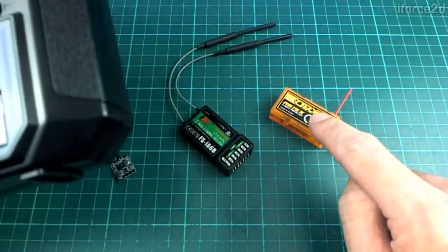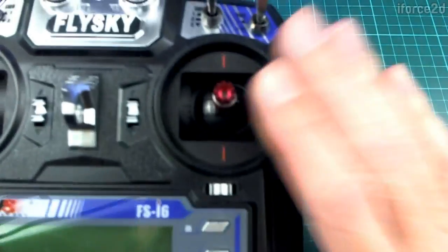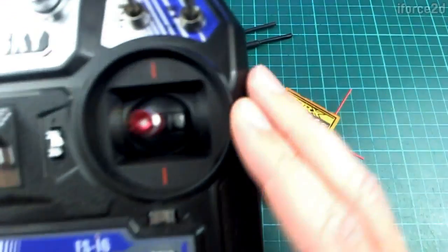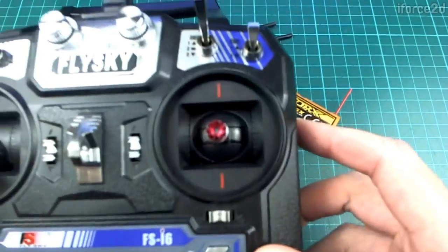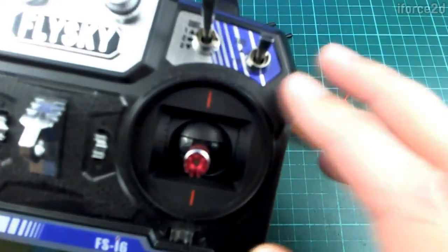And the orange one over here on the right, that is made to use a different radio protocol, so it's not going to work with this transmitter. So usually when you buy a radio like this, you'll find that it comes with a receiver quite often, and in that case you'll be fine. But if you buy extra receivers, you need to make sure you get the right one so that you can use it with your existing transmitter.